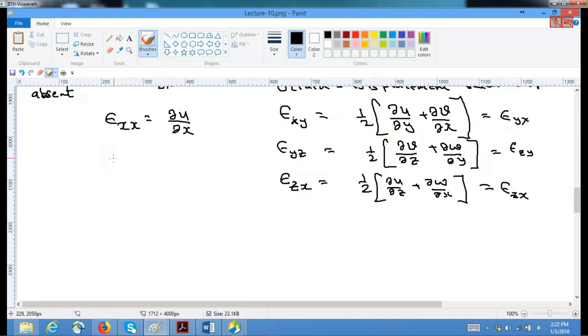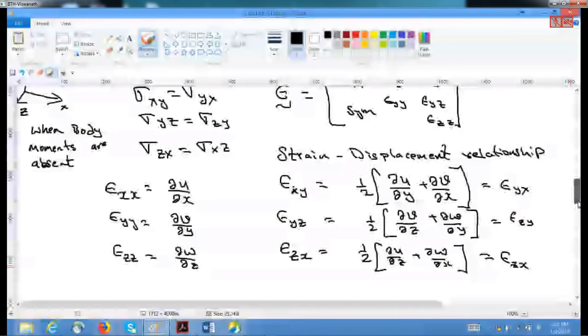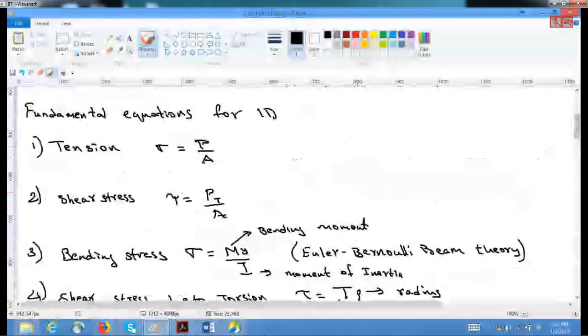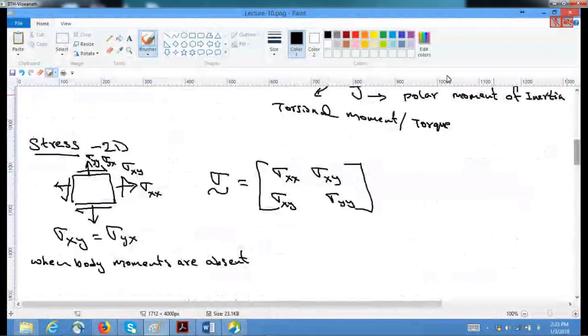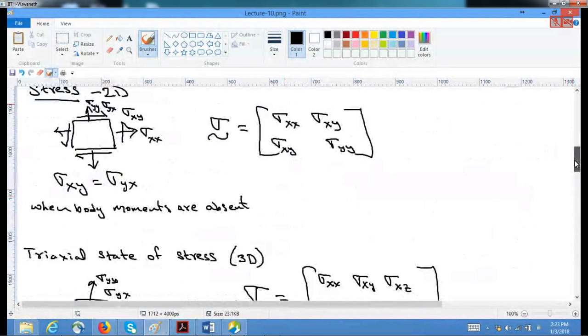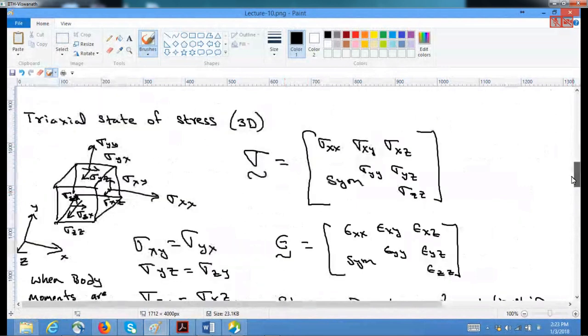Now, in a one-dimensional state, the stresses were much simpler, with only one component. Whereas in the two-dimensional state, you have three independent stresses: this is 1, this is 2, and this is 3. In the three-dimensional state, you have 1, 2, 3, 4, 5, 6. So depending upon how you want to analyze your continuum, if you analyze in a three-dimensional state, you have to deal with a higher number of stresses.